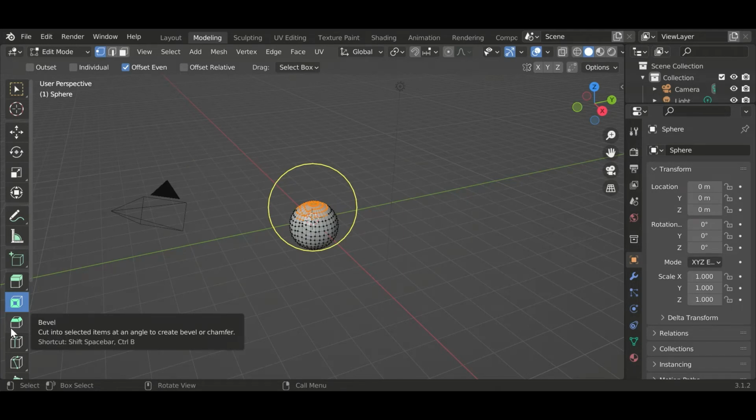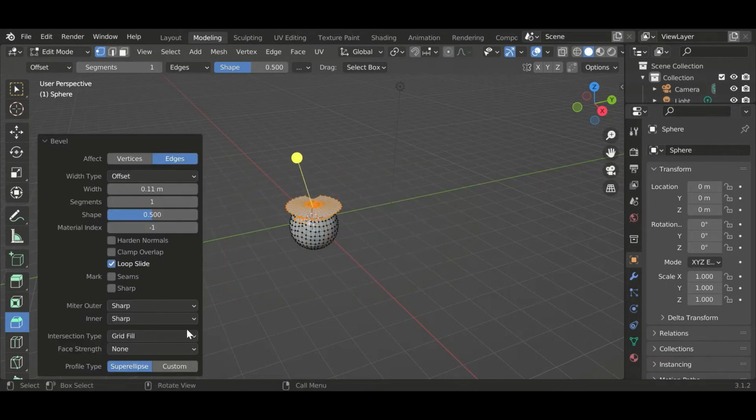The customizations for the bevel menu are: change whether it bevels the vertices or the edges, the method for calculating the size of the bevel once it is done, the width or strength of the bevel, the amount of segments for the bevel, the profile or shape topology of the bevel, the material that you use for the beveled faces, where the default -1 means resort to the adjacent faces for reference.